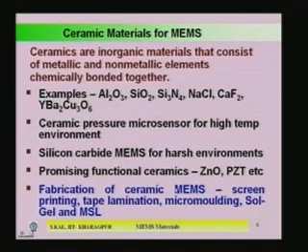Fabrication of ceramic MEMS, techniques used are screen printing, tape lamination, micro molding, sol gel and MSL. MSL stands for micro stereolithography.